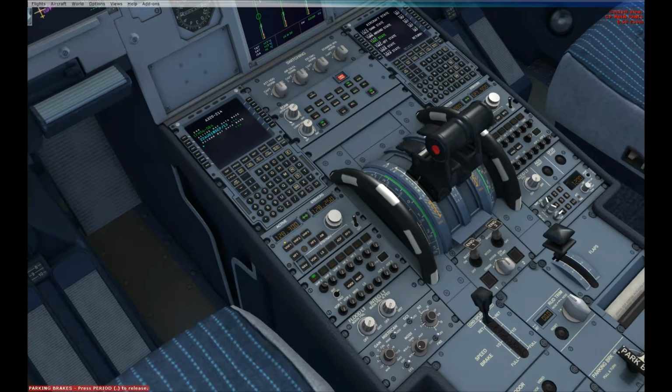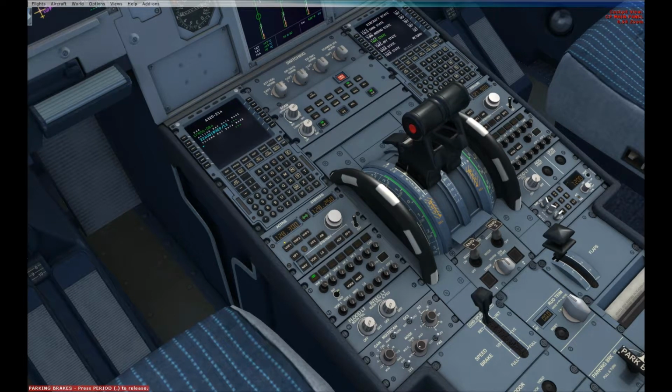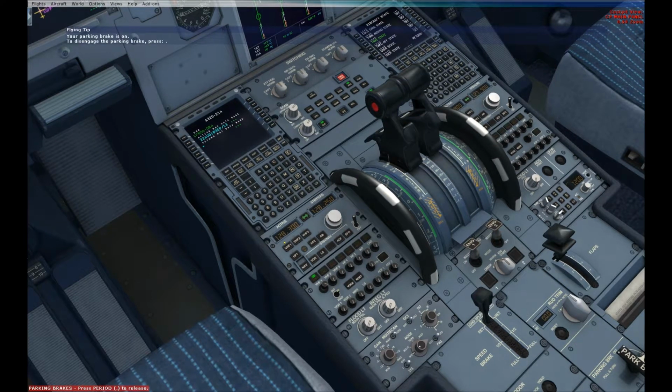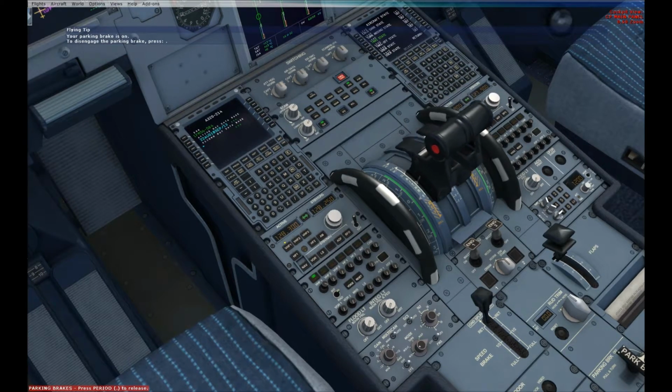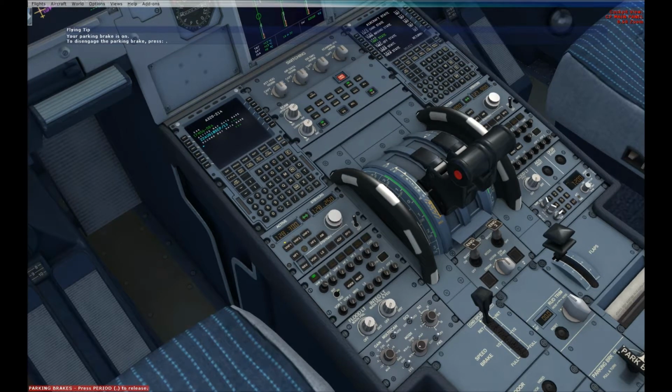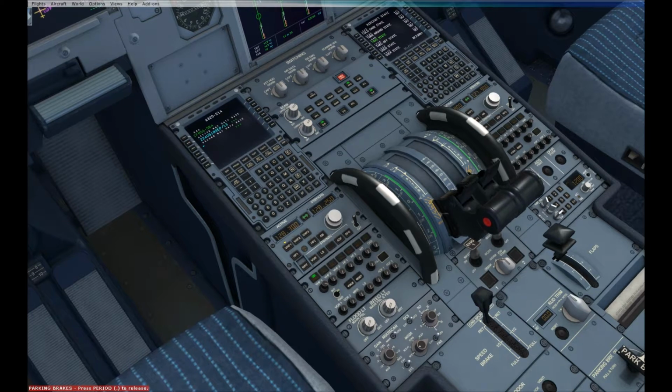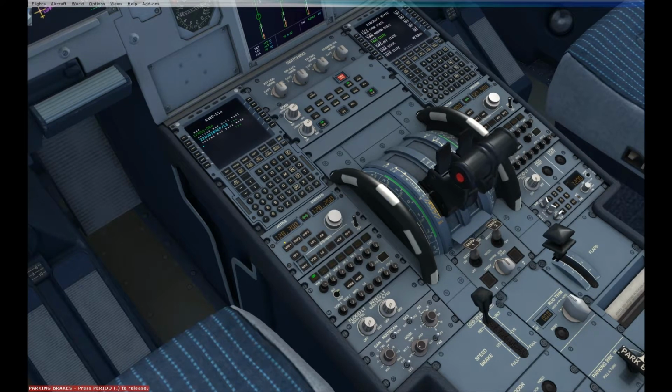The throttle quadrant is notched. It has 3 positions and clicks into the positions rather than being a continuous graduated increase. Reverse thrust operated by pulling the levers up and replaced to idle.